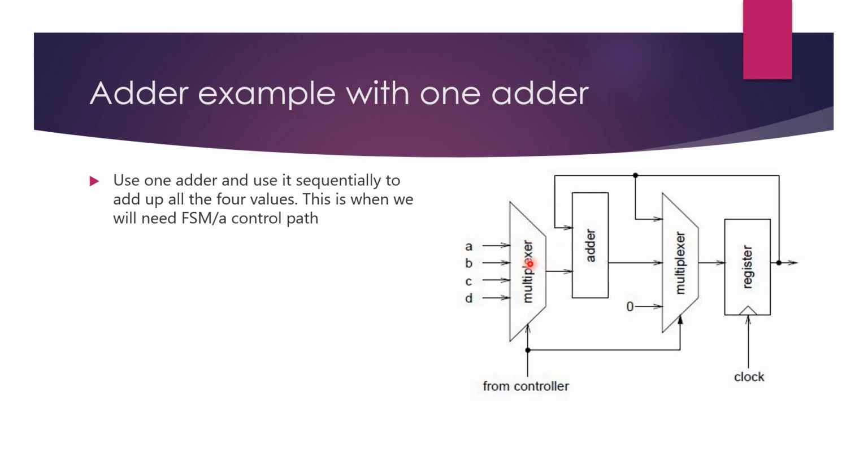There is something called a timing diagram. Do you all know what a timing diagram is? I want you to draw a clock, the register clock. Draw the inputs A, B, C, D, and name each of these nodes. Every clock, see how the node value changes. It's not an assignment, it's for your practice. Draw a timing diagram and find this output, call it O or Y, whatever you like. And every clock, see how the value of each node changes.